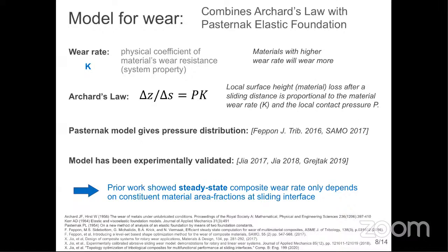And the most important thing you need to know for today is that by examining our model, we've previously shown that the steady state composite wear rate is dictated by the area fractions of the constituent materials at the sliding interface only. Transient run-in wear is a different story, but today I'm sticking with the simpler steady state. So in other words, if you know the area fractions of the constituent materials of your composite at the sliding interface, you can predict the steady state wear performance, the steady state composite wear rate.